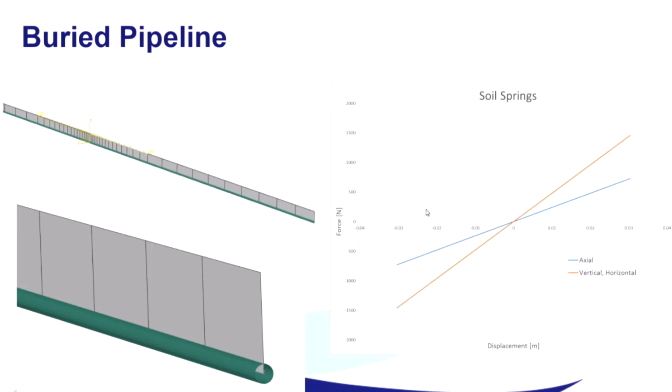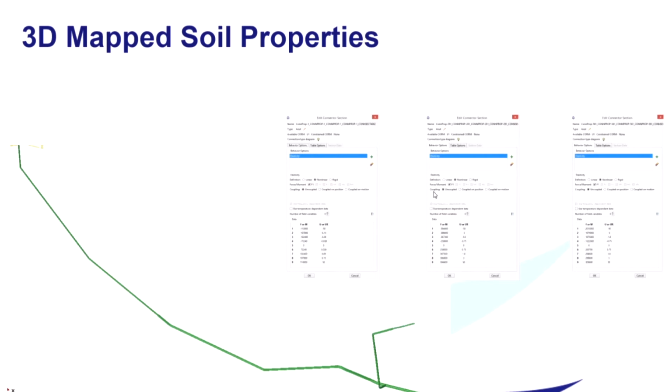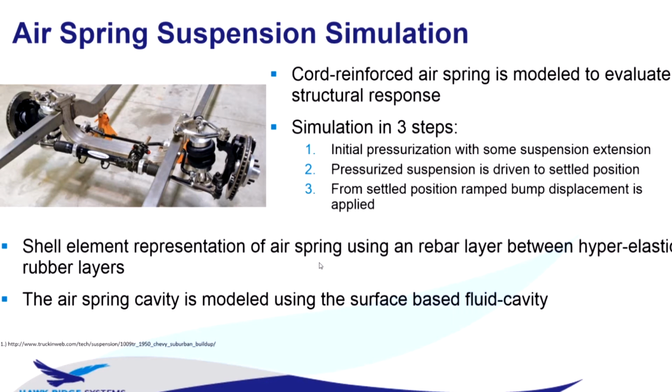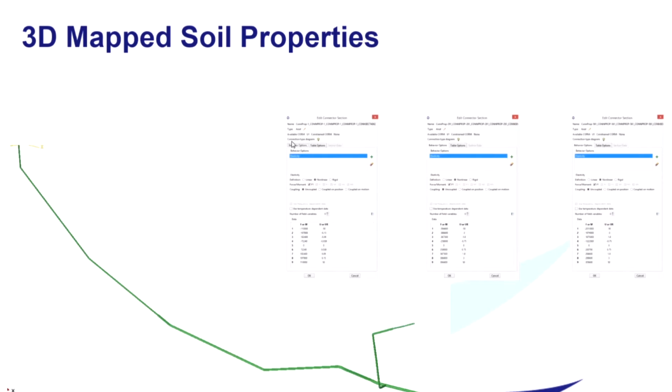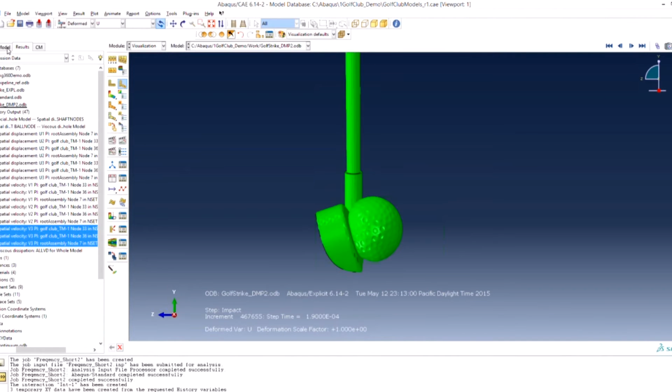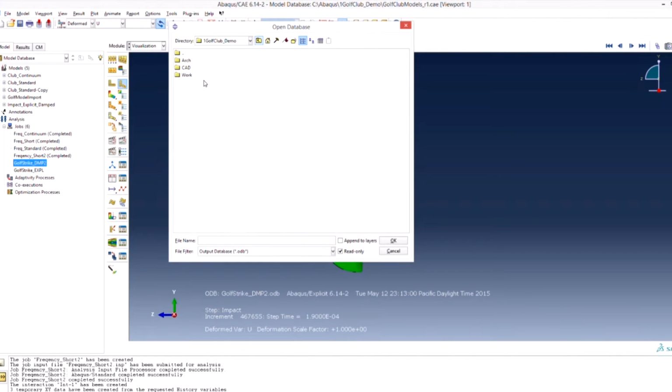So these models can resolve the ground properties, as well as you can measure them, in that we can have three-dimensional spring properties at every element along a fairly complicated pipe and soil system, so the resolution of this is really going to be as good as your measurements. So I'll show one of these types of pipeline models.